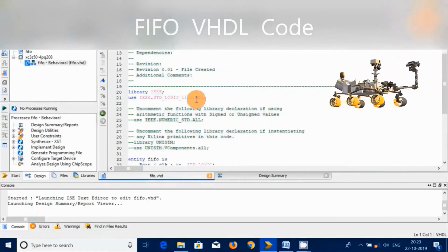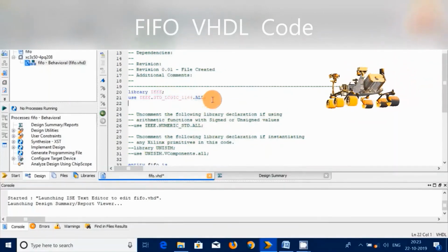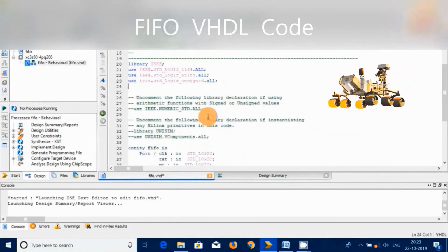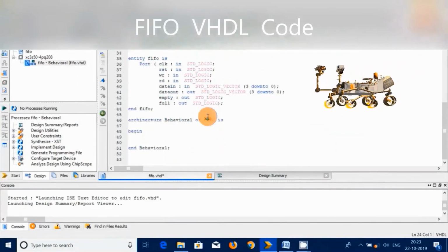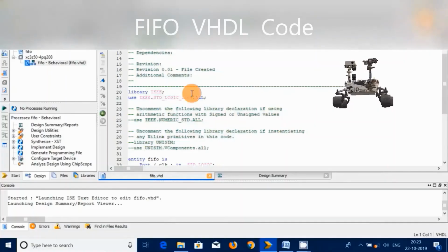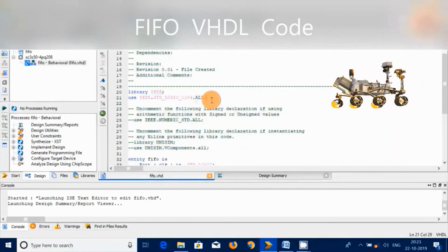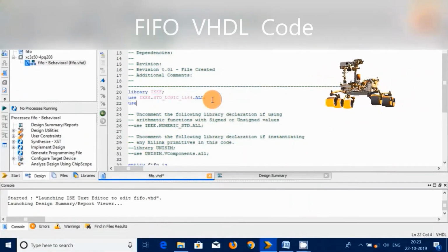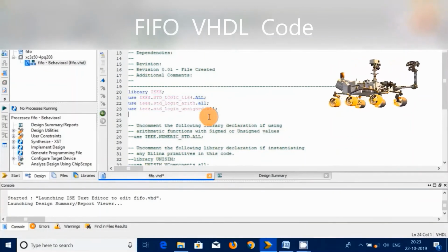In the standard FIFO, first in first out, when you write the first byte into the FIFO, nothing takes place on the data out bus until the read enable signal is pushed high for at least one clock cycle. Once the byte has been written into the FIFO, the empty flag will go low.